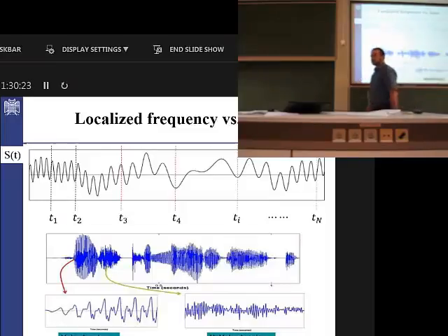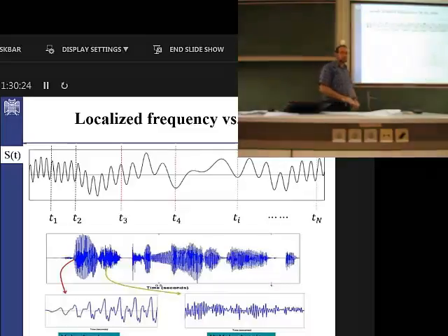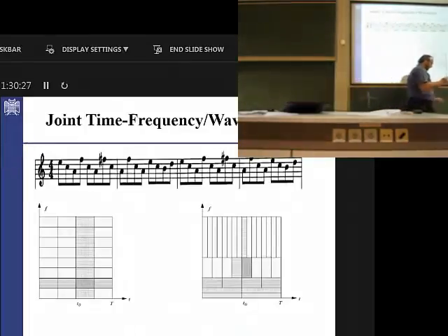That's why in wavelet it says that if you want the highest resolution over the lowest frequency, you need to have a very large window in the time. You can even go one level further to have the entire T, which takes the lowest possible frequency component.